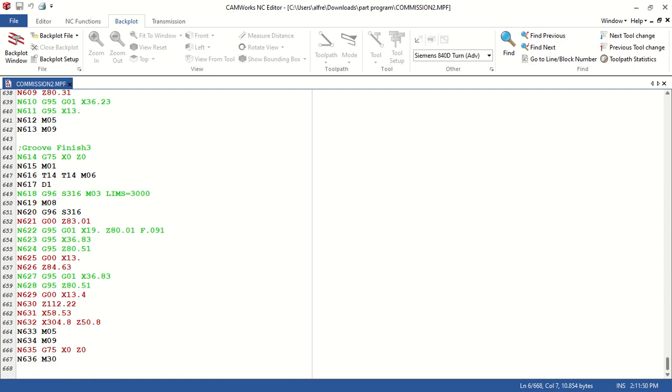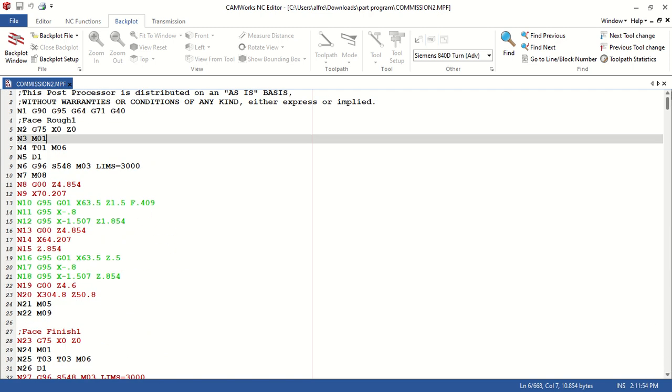So this is the G and M code of the program you have programmed. Ensure that this program, because it is for left spindle and right spindle, once the left spindle finishes, the right spindle can now take the part, and then the left tool starts turning from left to right. So left spindle uses the right tool, whatever position you are, it is coming either from the upper or lower side, turning from right to left. Then once it finishes, the right spindle takes over, and the left tool turns from left to right. That's how the operation will work.